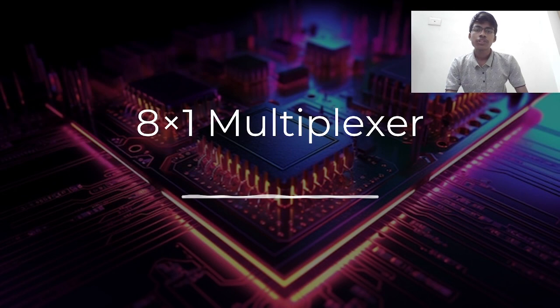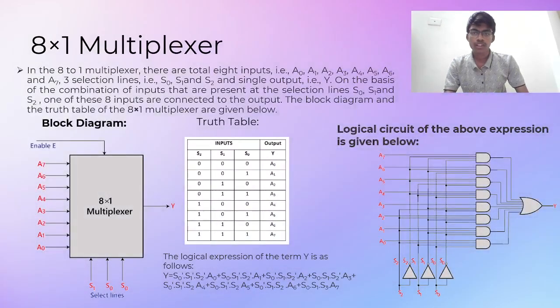Now let us look into the third basic multiplexer, the 8 cross 1 multiplexer. As the name suggests, it has 8 inputs and 3 select lines, because 8 inputs can be represented as 2 power 3, where 3 represents the number of select lines, and only one output. The basic truth table is given along with the logic expression, and the logic circuit of the above expression is given below. So hope that the concepts of 2 cross 1, 4 cross 1, 8 cross 1 multiplexer are clear. The main important thing which we need to notice is the use of enable in 8 cross 1 multiplexers.